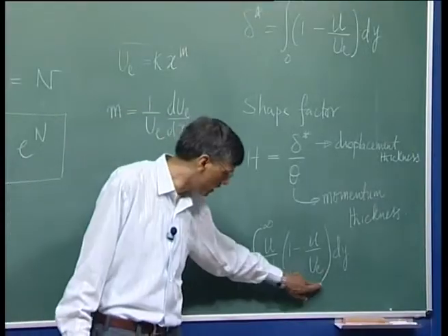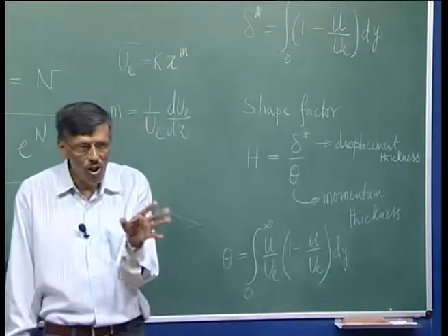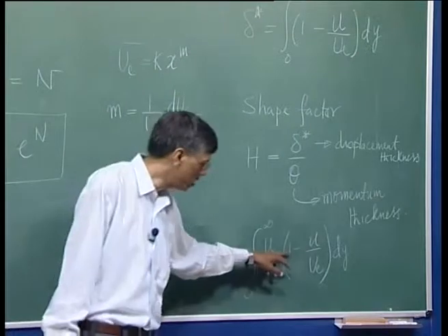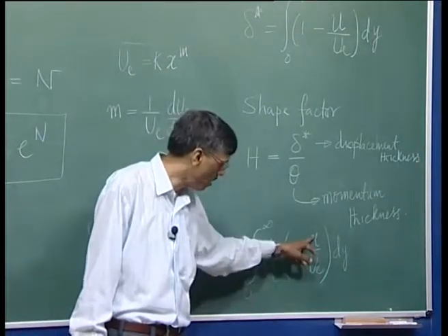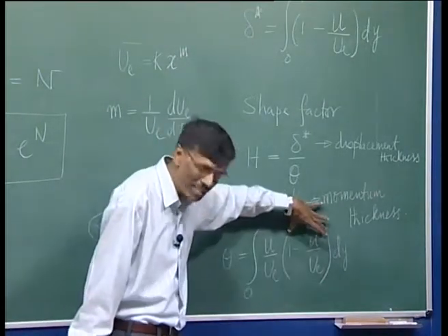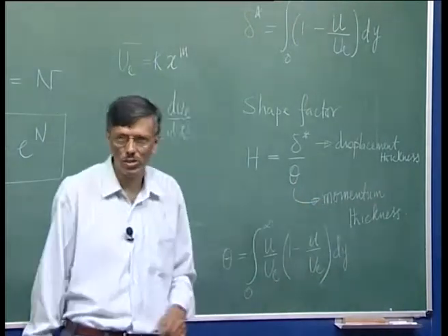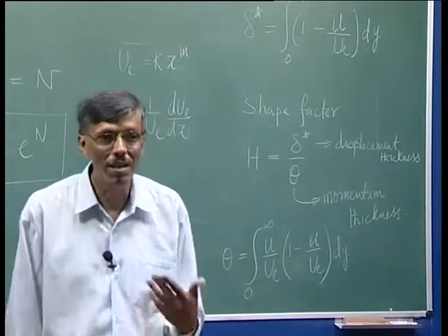Now, the second factor tells you the loss in this momentum because of viscous action. Ideally, it should have been 1, but it has come out to this. So, this is the kind of a loss. This is the actual mass flow times loss, so that will tell you about the momentum deficit.